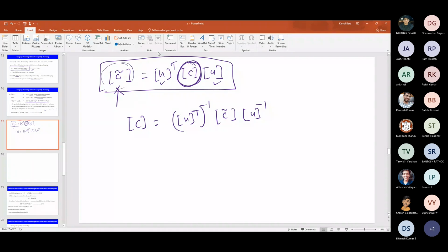That is the damping matrix I want to construct from the modal damping. This is the modal damping matrix, and this is our structural damping matrix. And this is the mode shape vector, that is the modal matrix U. Correct? I can find out, right? Now the question is how to find out this and this. So how will you find out? Everybody agree with me that this expression is coming from here?